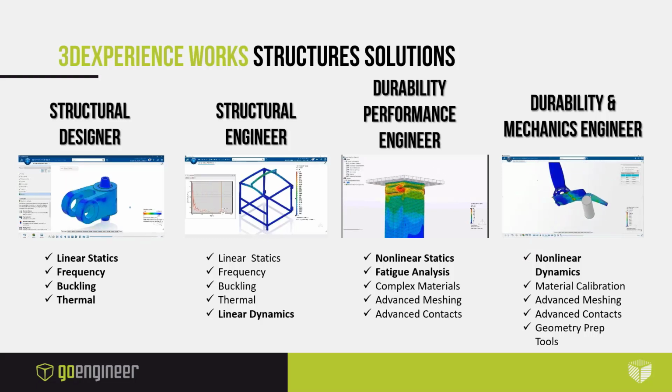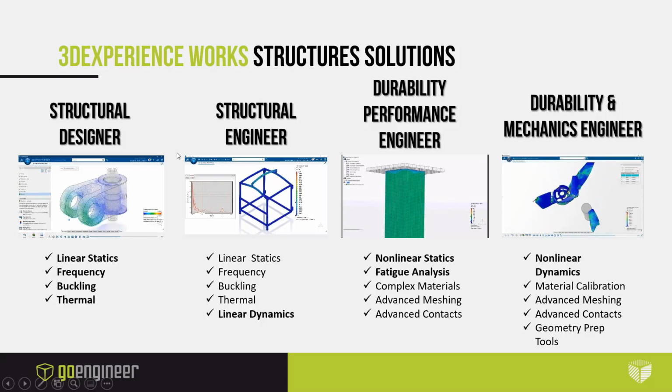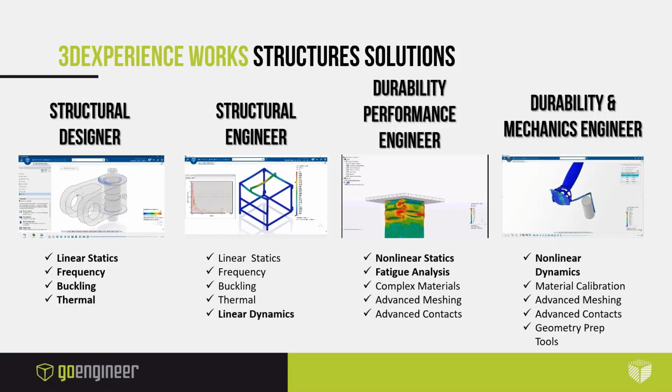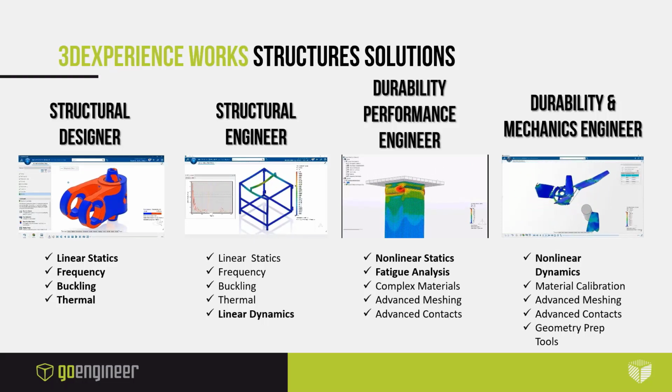Now, as far as the 3DEXPERIENCE platform goes, there are multiple tiers of structural solutions that you're able to adopt. The designer and the engineer tier gives you access to the Abaqus solver to solve linear statics and certain vibration problems. But when you get into the performance engineer and the mechanics engineer tier, that's where you get access to the nonlinear static and dynamic capabilities, where you're able to push the level of your analysis beyond an existing solution that you might have.